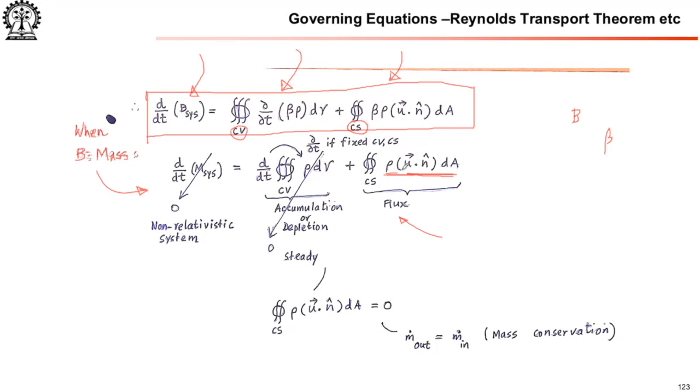Well, it's not the same surface. In some portions of the control volume surface mass is escaping, and in some portions new mass from adjoining area is coming. So you have to take the right local density, local velocity, and local surface normal at that location of the control volume surface, and then integrate over the entire surface of the control volume.